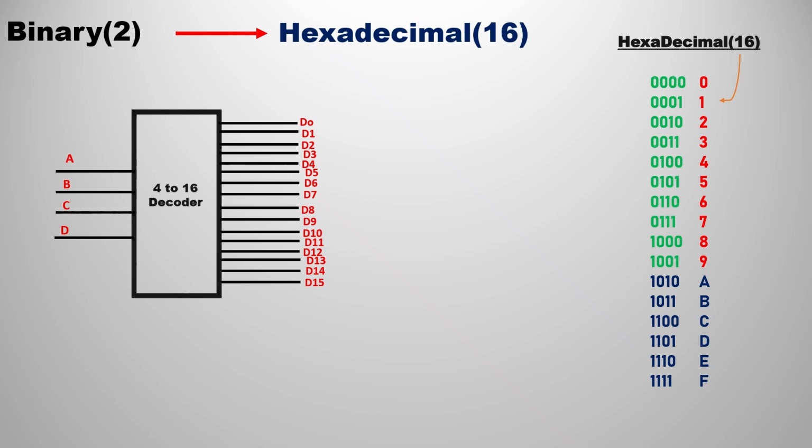But if you are not in decimal, you should not go like that. You have to go from 0 to 9, then after 9 you should not take double digits, you need to start with alphabets, that is A, B, C, D, E, F. You can also observe that I directly took 4 cross 16. In this case we do not have any trimming because we need all the 16 outputs, since this is hexadecimal.